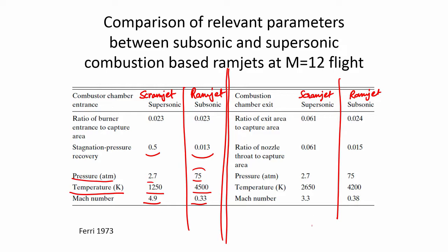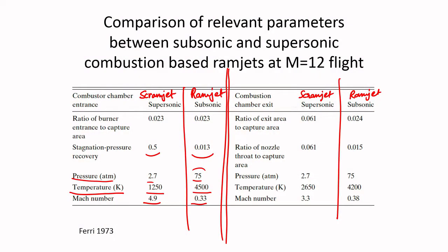So you see, this is the reason why ramjets cannot operate, that is, combustion cannot, because of the dissociation reactions essentially, and the fact that, even if there is no dissociation, the enthalpy that you can add to the flow by combustion is minuscule compared to the enthalpy that is already present in the flow, at least in terms of the thermal energy.